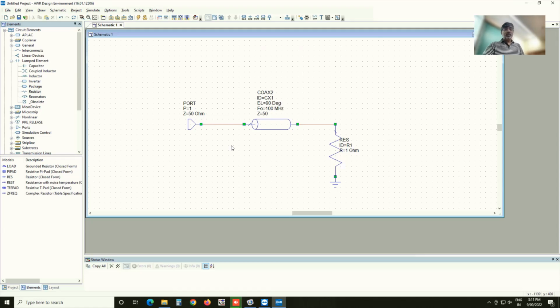Now, because I've been going on and on about wires having a different meaning at microwave frequencies: these red colored things which are connecting two terminals have no meaning. They are basically zero-length wires, even if they are finite length in this diagram. That's just for drawing purposes. But this piece of transmission line has a meaning in the sense that it is defined by these particular properties.